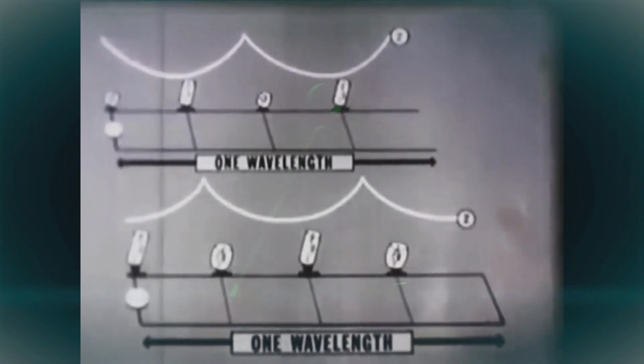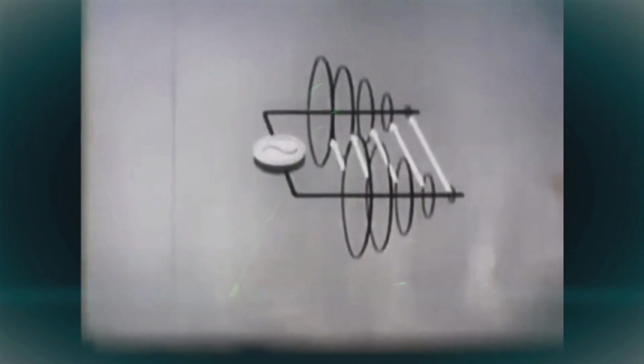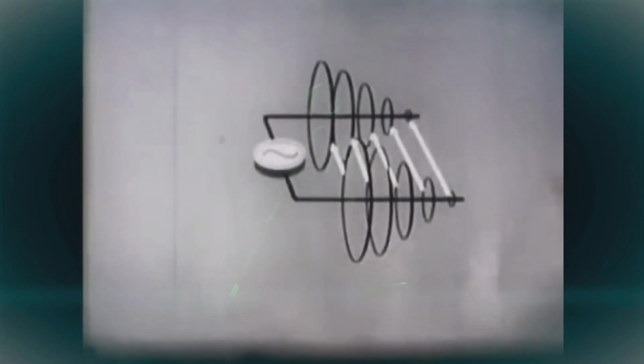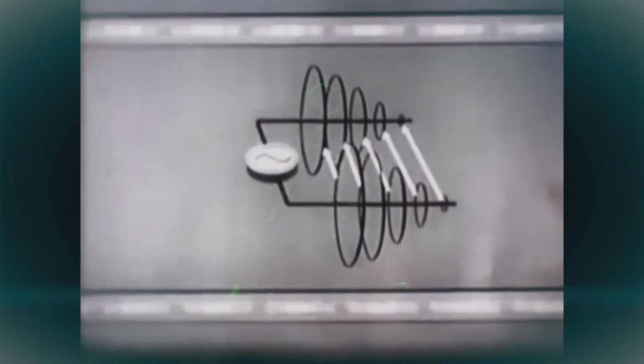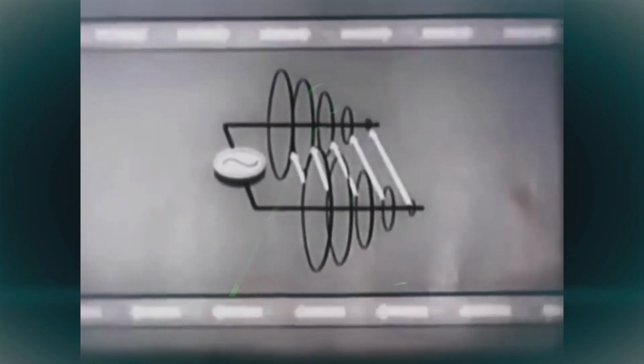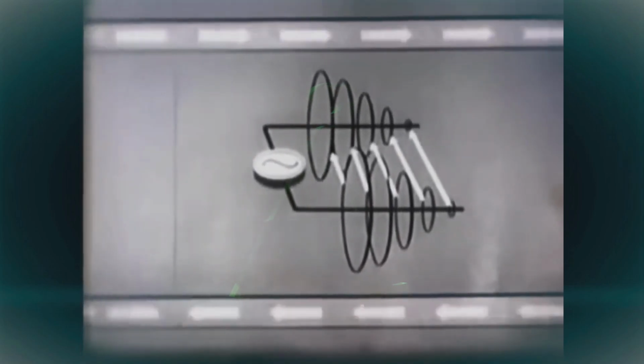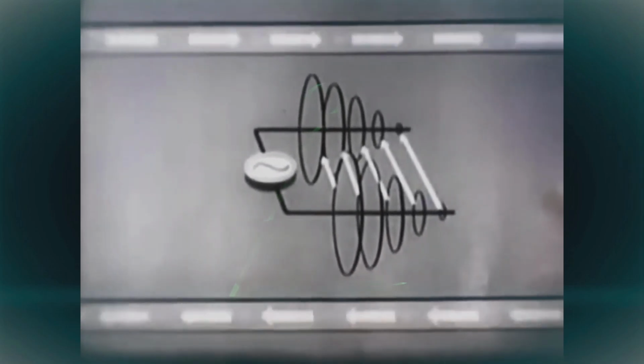Because of this facility, they are known as resonant lines or tuned lines. In this 1/4 wavelength of open transmission line, we have the requirements for a radio antenna. Let's take a quick look at the electric field here. Because the current flows in opposite directions in the two conductors, the directions of the magnetic fields are opposite, and any radiation is canceled.